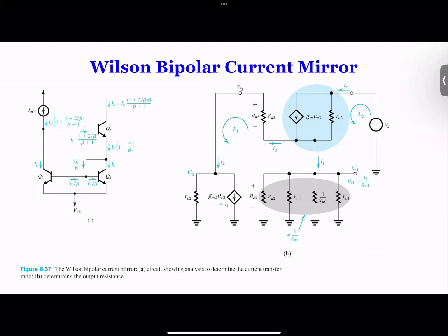So once you find the current relations, the other thing is, we know the current source that we discussed so far. For small signal, the DC current source becomes an open circuit, but what's left is its output resistance, and that resistance is pretty high. It's usually RO of the MOSFET or BJT. So we use that as a load to amplify, to increase the gain and things like that. So how does this look when you get into the small signal, what's left, right?